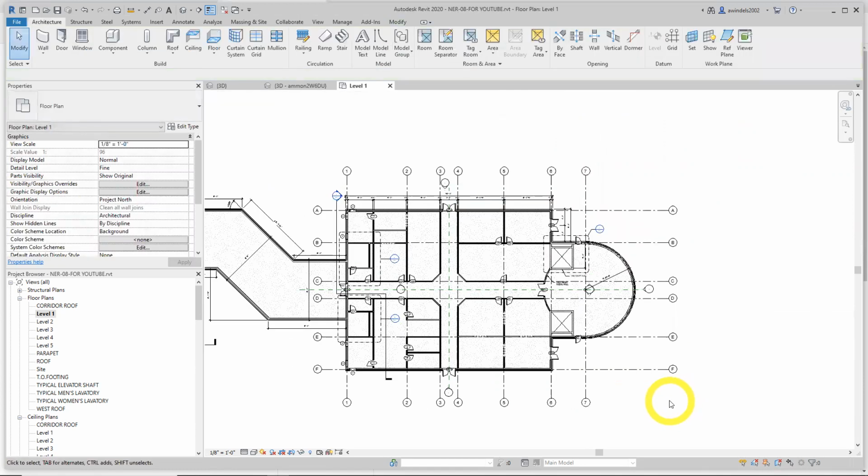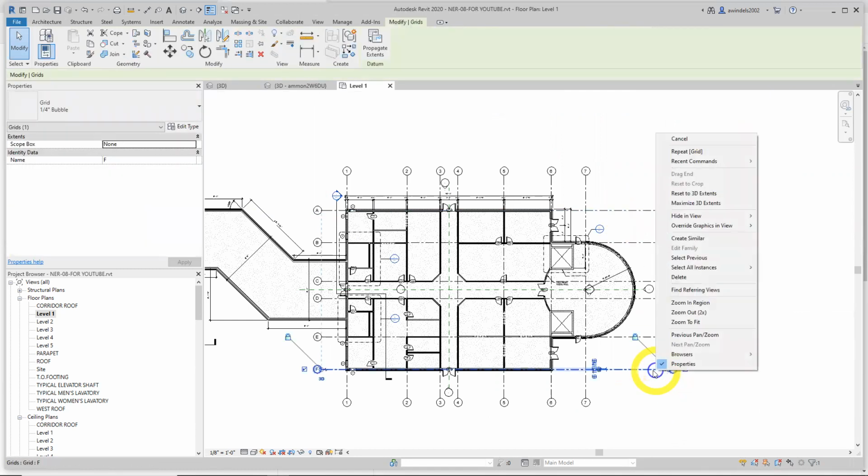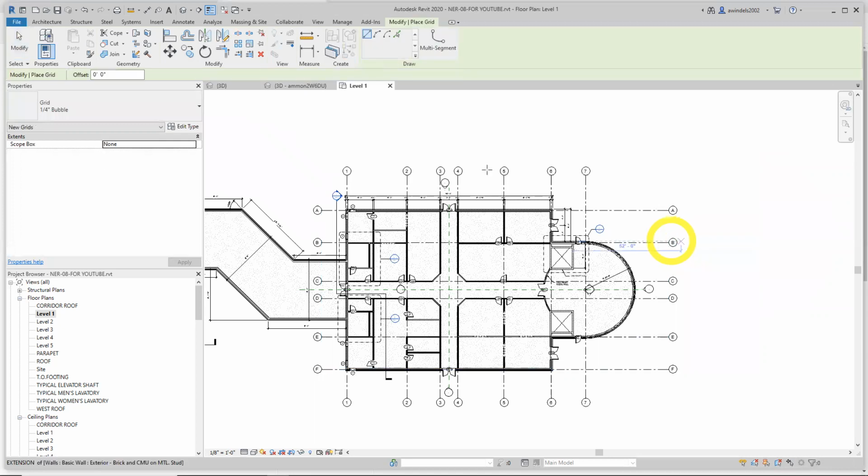So we got our grids going through page 381. We're going to try adding a radial grid, G, which is a unique shape. So let's try to create similar again. On the draw panel this time, we're going to say pick lines again, but let's go here, take the F, right, similar. This time, let's put a 6-inch offset and say pick line again.